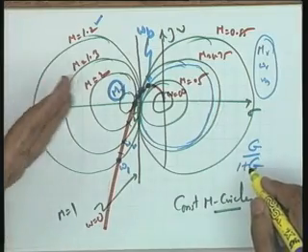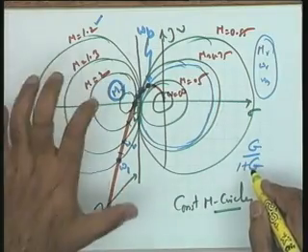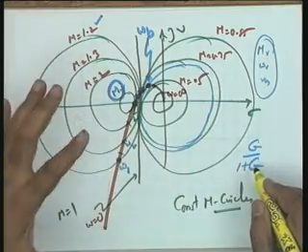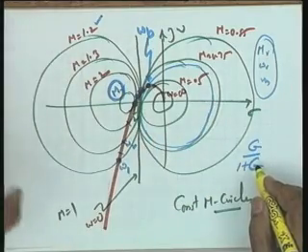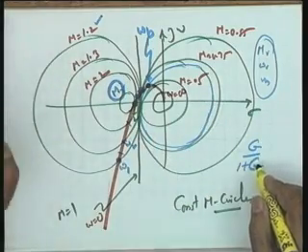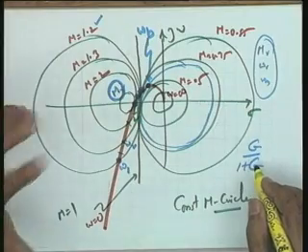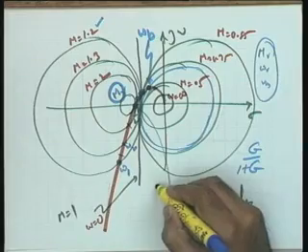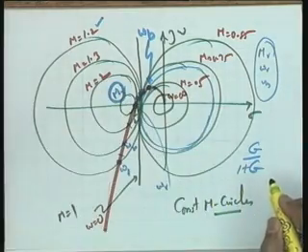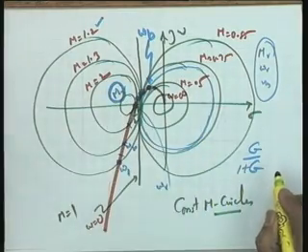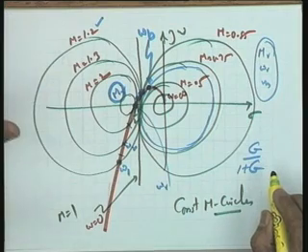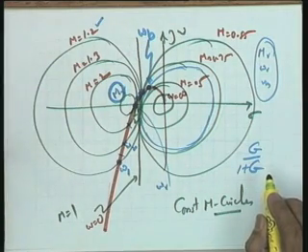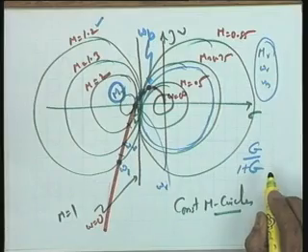So, with this now, though I am going to give you an alternative to M circles, I have concluded that all the indices, the phase margin, the gain margin, Mr, omega r, where this corresponding frequency is omega r, of course, where it is tangent, and omega b, all these indices we are now able to obtain from the open loop frequency response data. So, as such, our analysis problem is complete, okay.